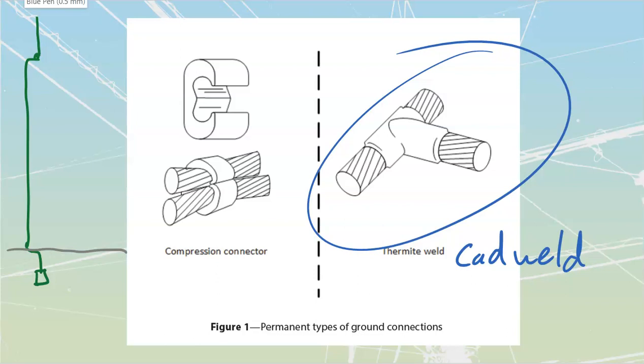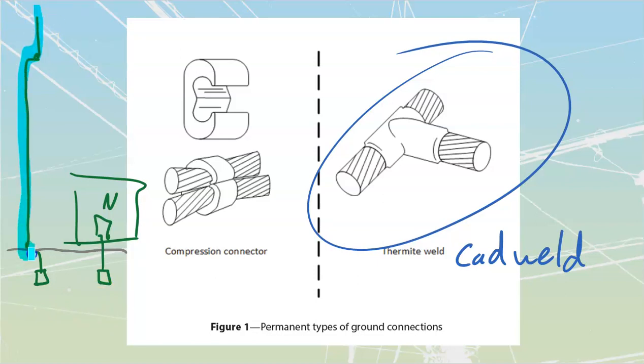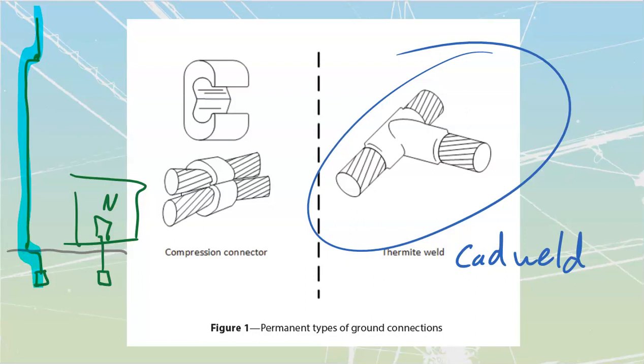What I'm also going to have inside of that building is my regular grounding system. And my regular grounding system is going to be attached to the neutral that's going to be inside of my system and of all of my electrical distribution. These two do need to be at least 2 meters apart. We sometimes have other ones for CATV or for telephone, but these are the most common ones that we would have. They want to keep them 2 meters apart because in the event of a lightning strike, we get mass amounts of current that are going to get dumped through here. And as a result of that, we're going to get what are referred to as step voltages. These are going to be rings of voltage that are around the outside.